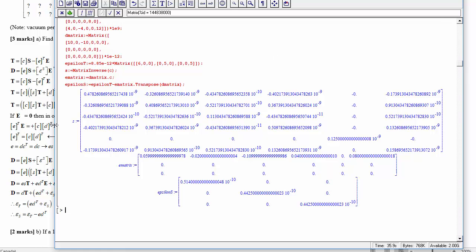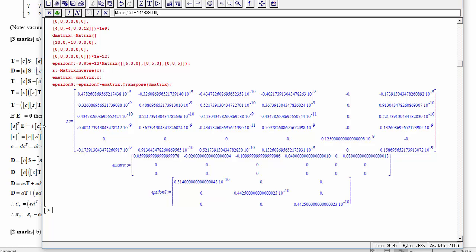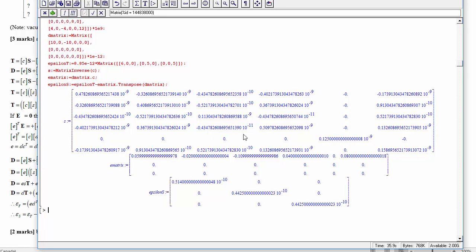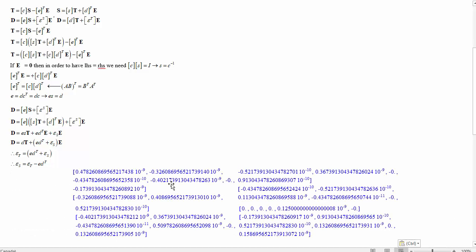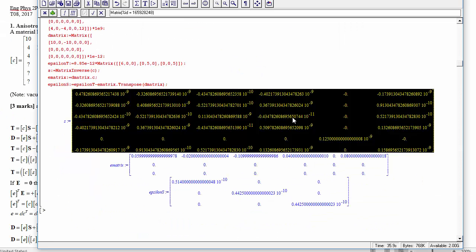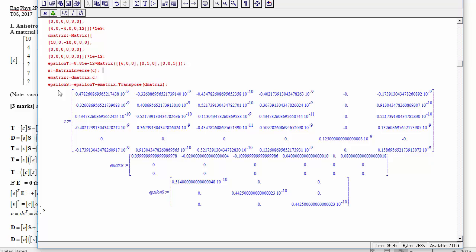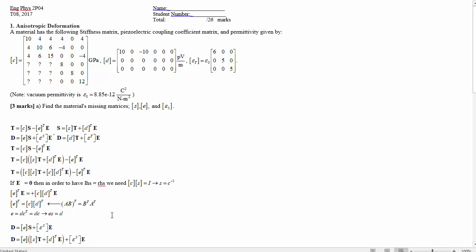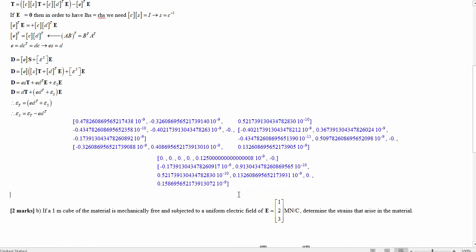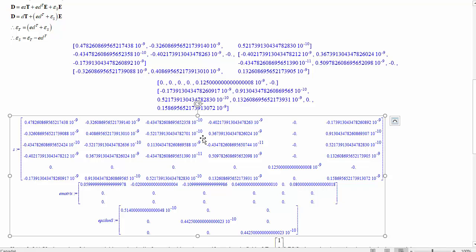And one way to get this to copy over, if you want to have a neat picture of the matrix and not include so many different significant figures: I find that Maple often, at least in this version, doesn't elegantly copy these matrices over. It'll say, in order to get this over, we've got to make a bunch of little pieces of it. So what you can do is just do a screen clip of it. Take whatever your favorite screen clipping program is. This is Evernote that I'm using here, but you can use the snipping tool, whatever you're interested in, and then copy that over, and then you've got a nice, more compact picture of the matrix with all the significant figures.